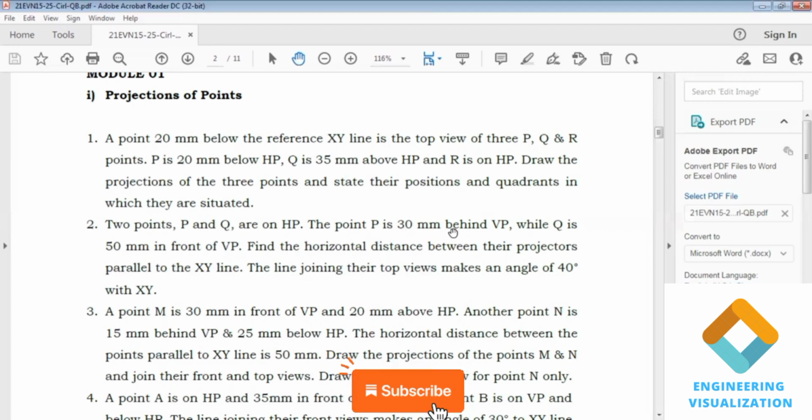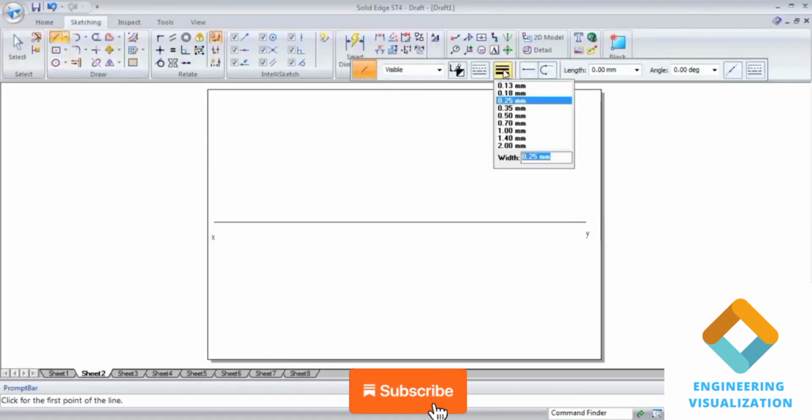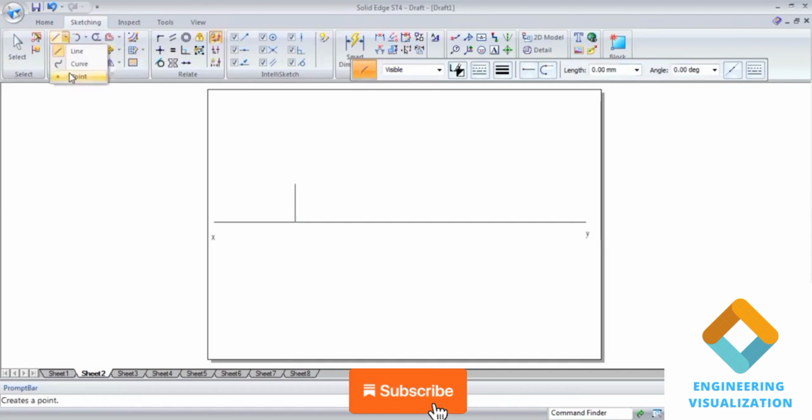Point P is 30 mm behind VP. Behind VP means two chances, second and third quadrant. In second and third quadrant, the top view is lying above the XY line. So mention the dimension and put a point.